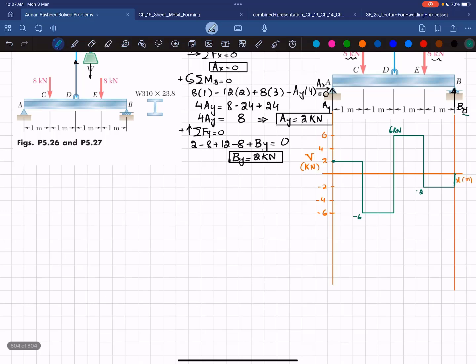And for the bending moment diagram, you have to draw a horizontal line to show length x in meters, and on the y-axis you have moment which will be in kilonewton meters. Okay, so what we will take is that one division is equal to 2, so 4 kilonewton meters. Similarly -2, -4, and this is -6. Okay, starting from the first point, at point A, as x is equal to 0, moment will be equal to 0.